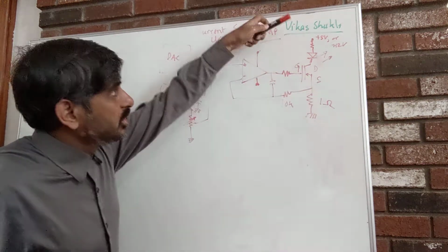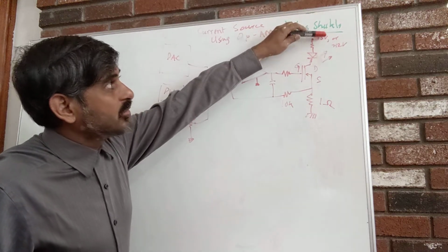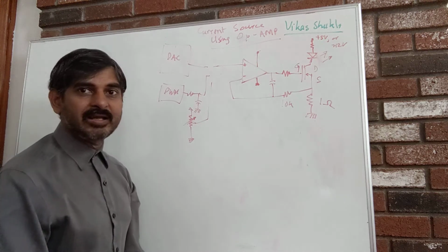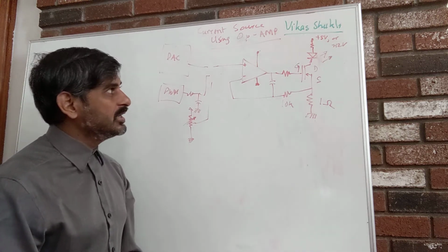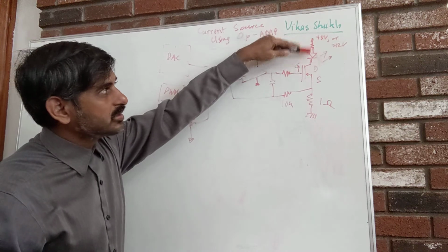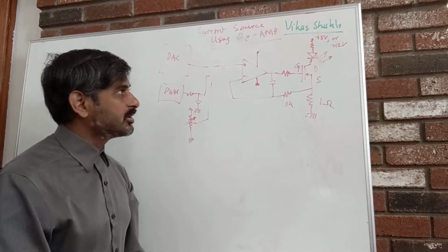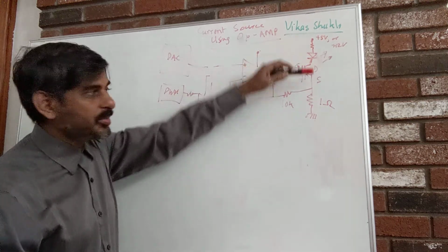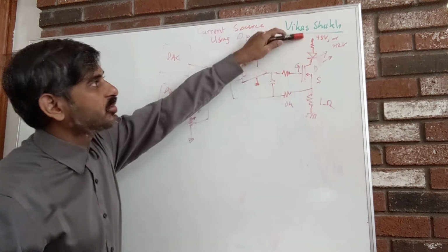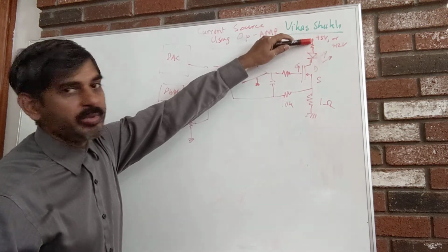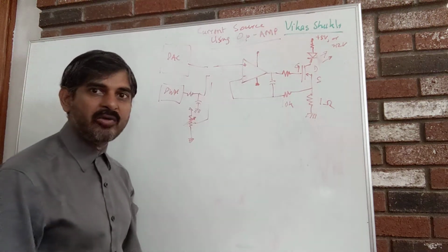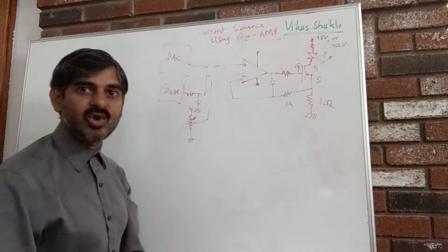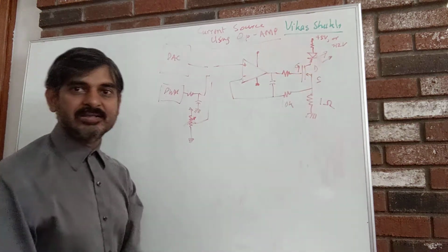Other than that, we need to look at this voltage level here. It should be suitably selected, higher than what you need to get this LED turned on. For example, you should consider the D to S voltage drop here, and if you are using any resistor here, some voltage drop there. If you use a too high voltage, then the D to S voltage will be too high, and this FET or the transistor gets too hot.